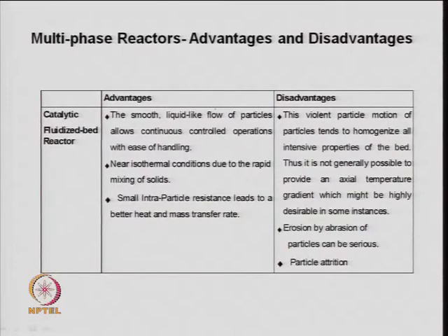The only thing is that you need some high flow rate or superficial gas velocity, and all these hydrodynamic studies need to be done in order to keep the bed fluidized at all times. This allows a continuous controlled operation with ease of handling. Particles can be removed from the system, and they are well in contact with the reactant. So, the heat transfer and mass transfer problems can be solved to some extent.